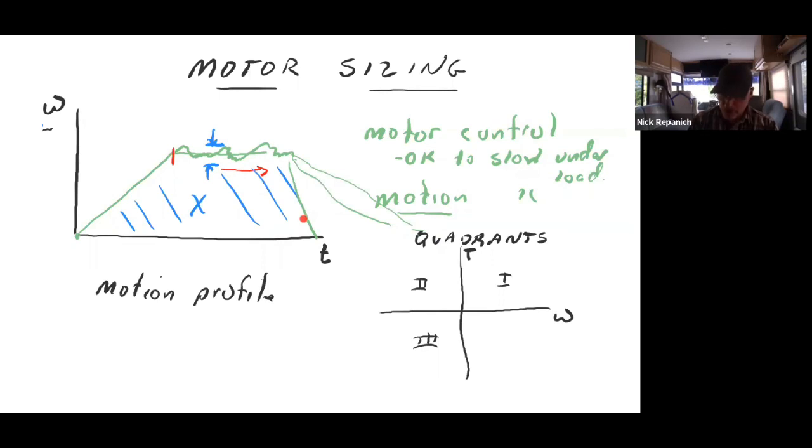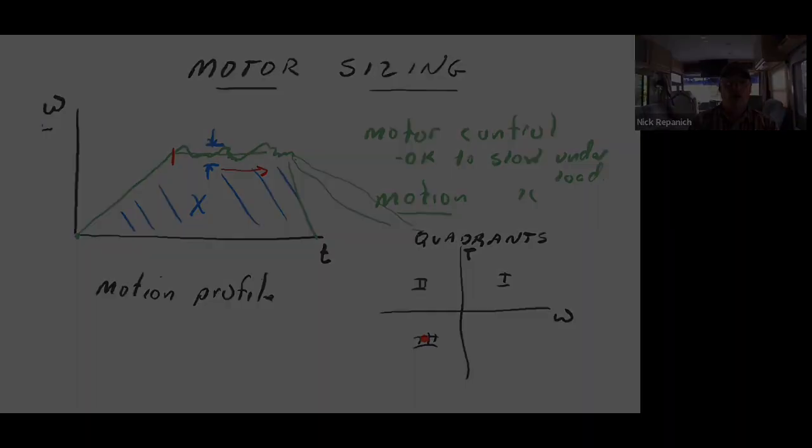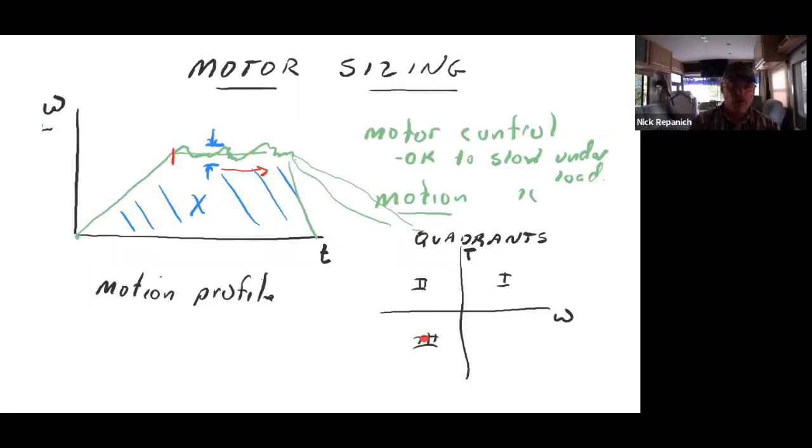So far, we haven't ventured over to this side yet, because this side is when you do what in your car? In reverse. If you were to plot reverse on a motion profile, let's say this is where you stop, you would say, okay, we're going to pause for a short period of time, and now we're going to do a reverse move, right? We're going to reverse and back into that spot. So your overall motion profile would go negative. Your speed essentially would go negative down here. That's what a negative motion profile would look like.